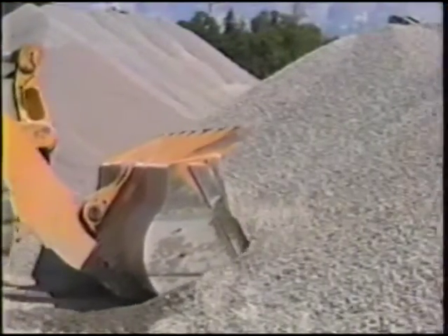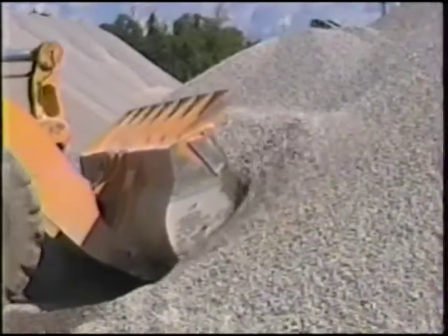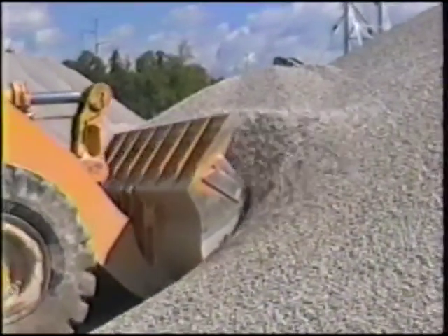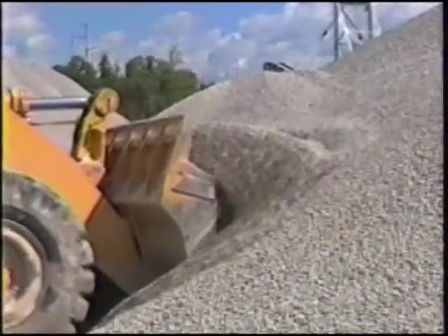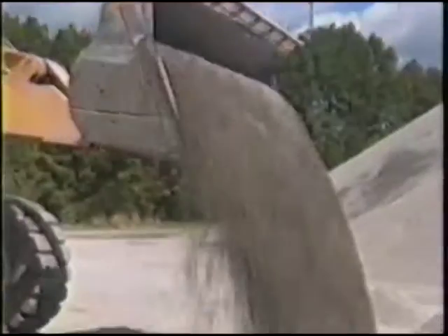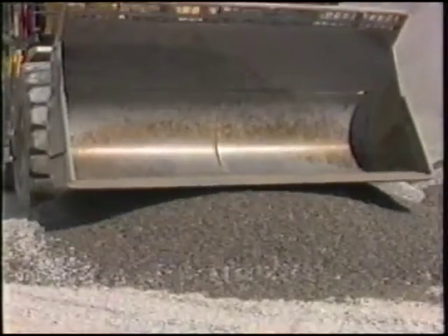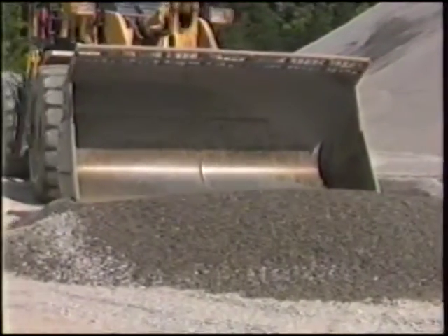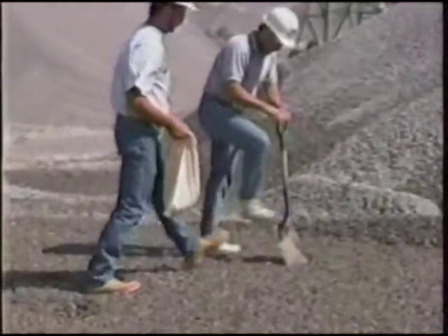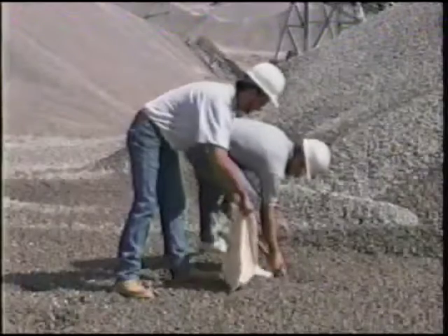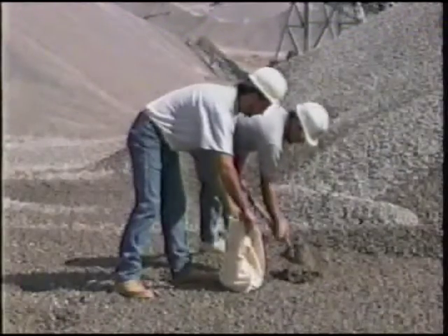The most commonly used sampling method is miniature stockpile sampling. A loader operator builds a miniature stockpile by digging into the pile and pulling out material to make a smaller pile. After the loader mixes the miniature stockpile, it should be back-dragged. Samples are taken at 3 randomly selected points within the top of the miniature stockpile.